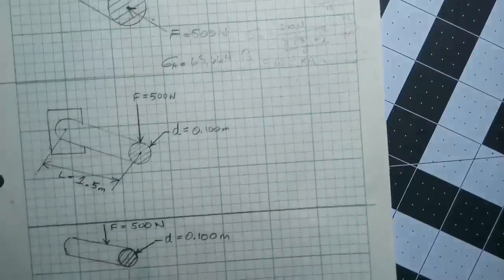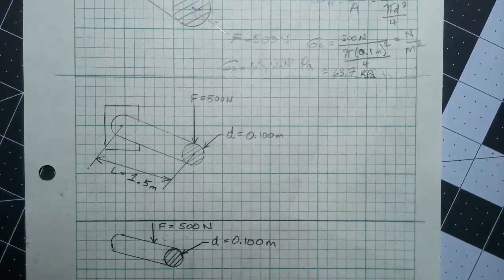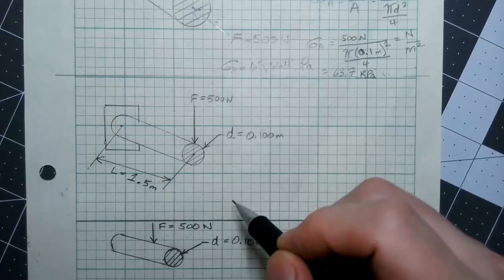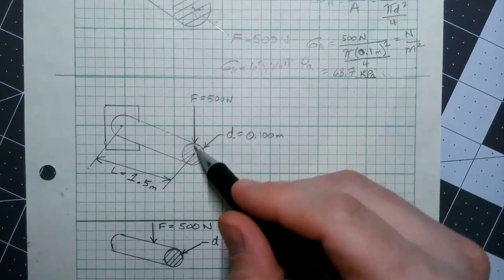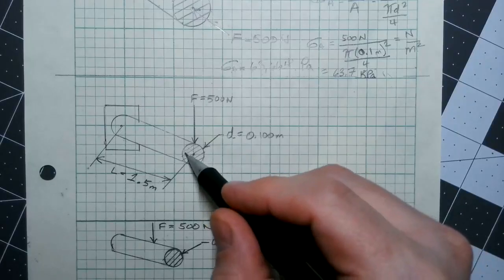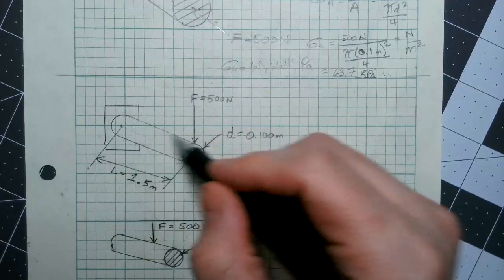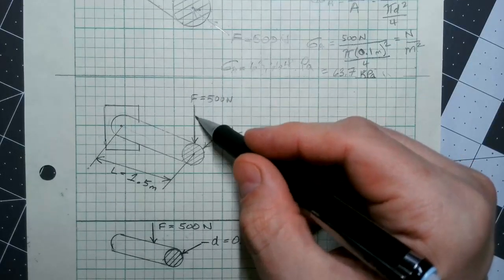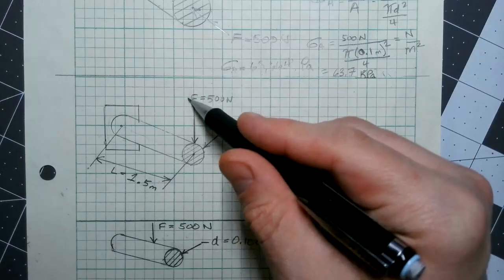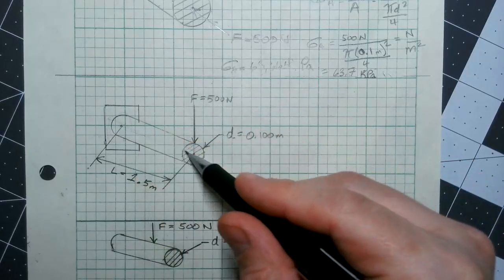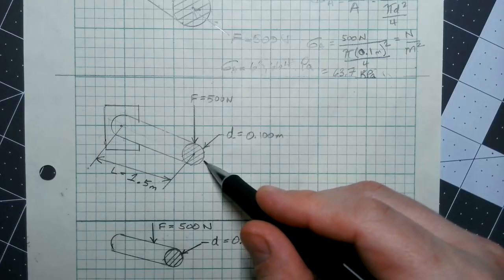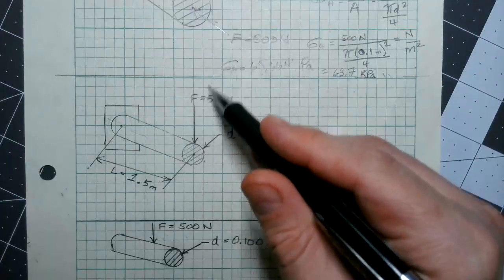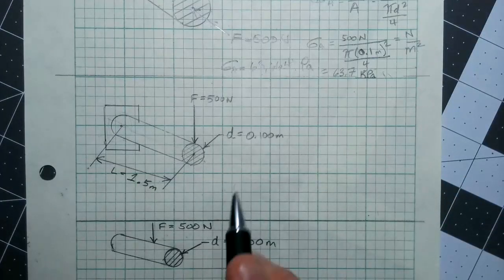Okay, next one to look at. See it? This is a case of what type of stress? Let's see. We've got a cylinder that is attached to a wall. It is free at this end. You have a force pushing down on the end such that it wants to try to bend it along the longitudinal axis. So it's trying to bend the axis, push it down. That's a definition of bending stress.